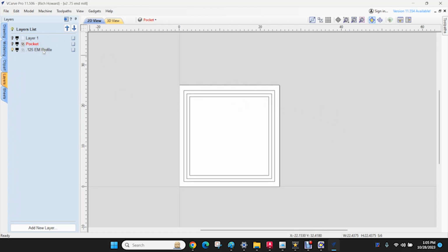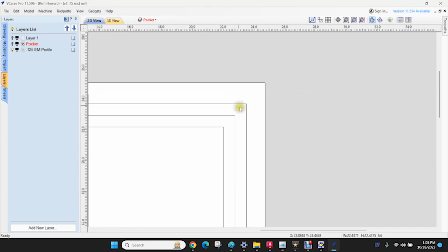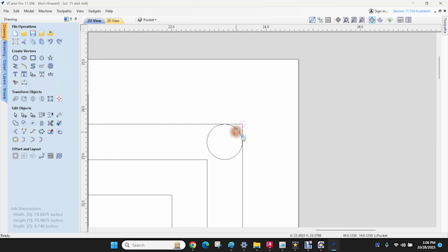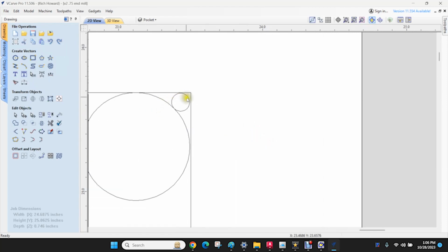So it's all about the radius corner. I'm going to have a 3/4 inch diameter bit pocketing all of that out, but I don't want a 3/8 radius in these corners. I want to see 0.0625. I want to see a tiny radius. So small, you're going to think it's square.